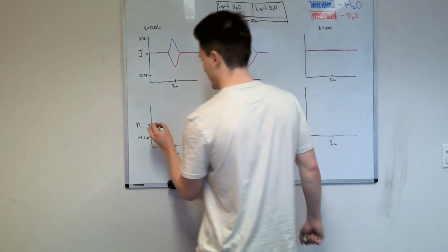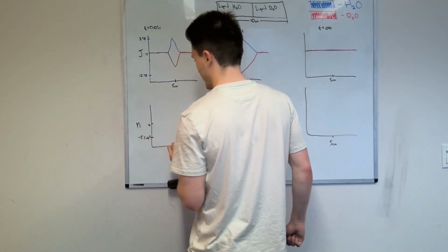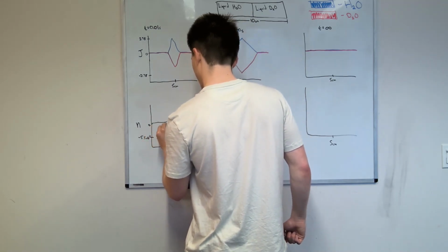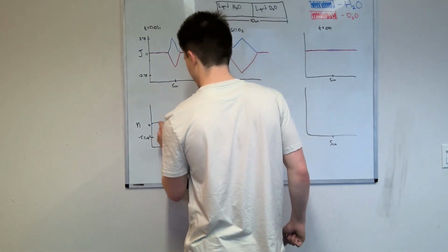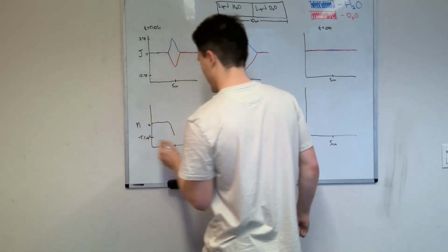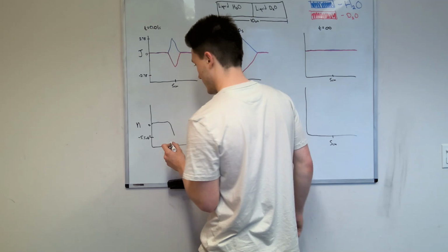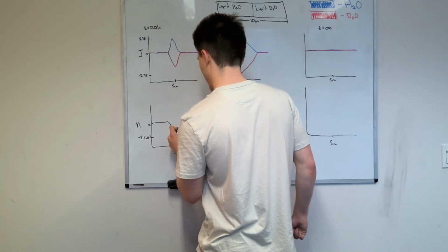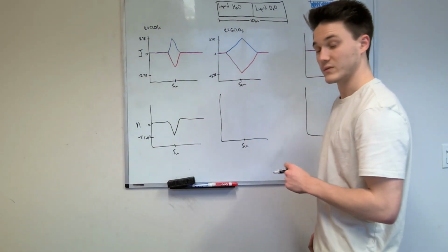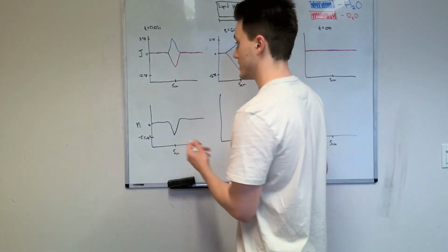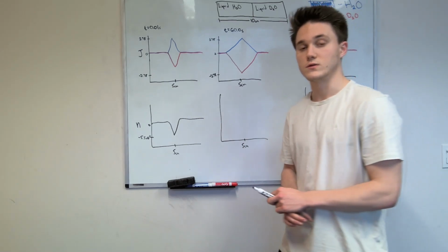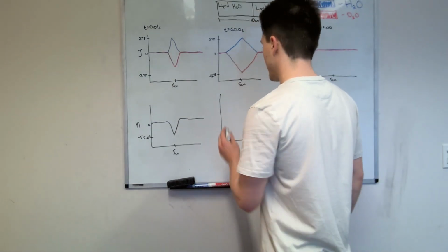And so this graph, initially at point 0, starts out at 0, and then as it reaches the halfway mark where these two liquids are starting to mix, it dips down to the negative 5.5 × 10^-3, which is the total mass flux, and then goes back up to 0, and then continues on. And the reason for the steepness in this slope is because this is the initial condition, and at this point, 5 centimeters, both the two liquids are starting to mix at the most rate.